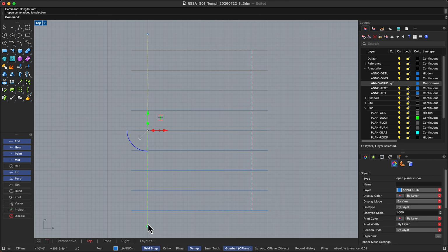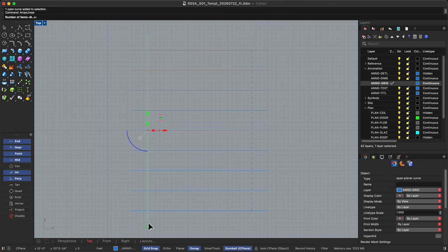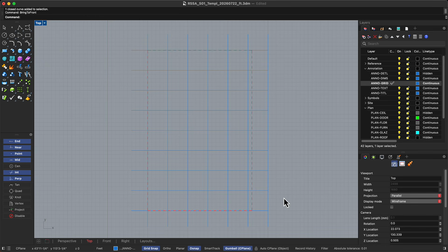The idea is that we'll be using a 5 by 5 foot module in the imperial file, or approximately 1.5 by 1.5 meters in the metric file. Working with a modular grid can help guide early decisions about room sizes, structural rhythm, and circulation. You could also use a smaller 4 foot or 1.2 meter module for more flexibility.